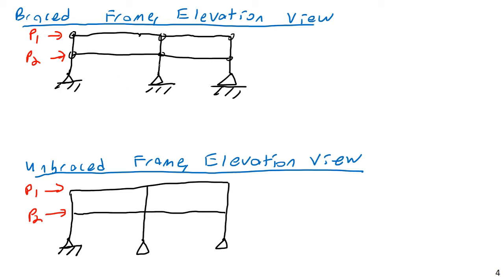Now, these of course are structural elements, they're not literally going to have pins, but if you want to get a sense of this, take some simple wooden sticks and connect them together with tape. Create a little cube and imagine pushing against it on its side, and you can see how, if everything in a frame is a pin connection, they're really not capable of resisting any kind of lateral load. What this thing's going to want to do is just flop over.